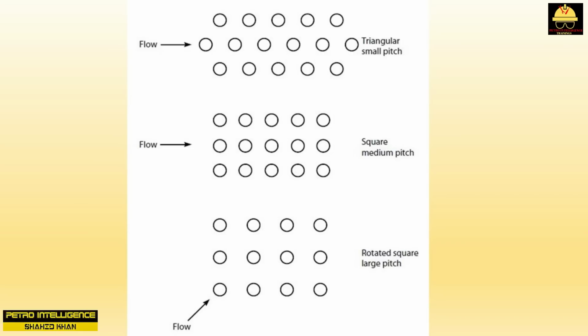The large tubes, and especially the doubling of the space between the tubes, reduce the heat transfer surface area that can fit into a shell of a given ID. But the primary objective of the 1-inch tubes on a 1.5-inch rotated square pitch is that it is relatively easy to hydroblast. Note that 1-inch tubes on a 1.5-inch tube pitch are 0.5-inch apart. 1-inch tubes on a 1.25-inch tube pitch are 0.25-inch apart. The larger spacing greatly reduces the tendency for fouling deposits to bridge the gap between the tubes.